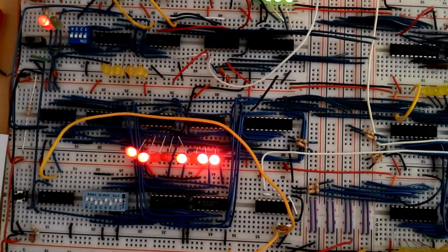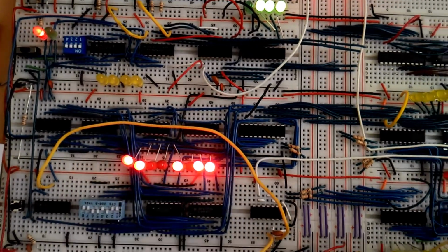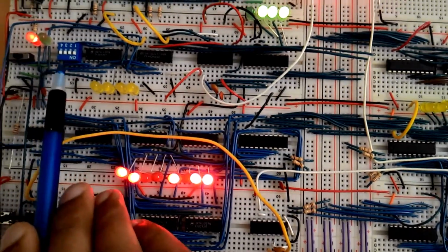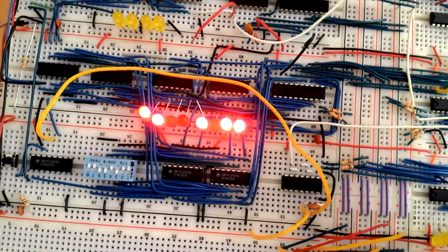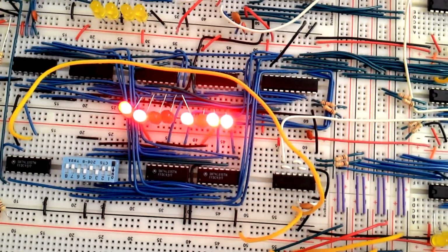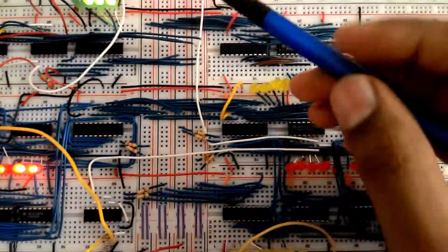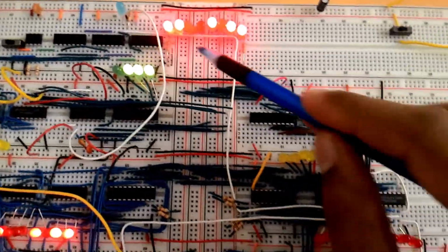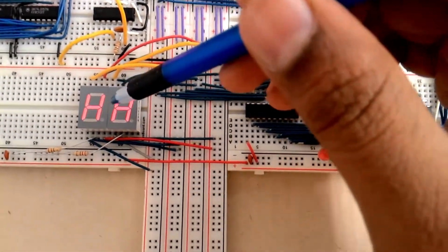What I'm going to do is that we know that our RAM module can store 8 bits of data. By using the memory address register, I can choose between 0 to 15, or 1 to 16 in decimal value, and then I can bring that data to our bus over here, and I have connected that bus value to the 7-segment display.